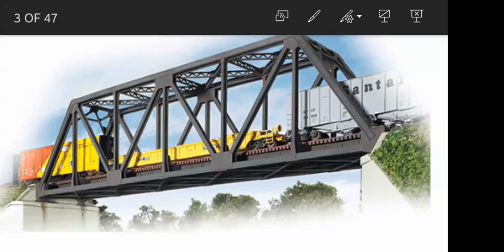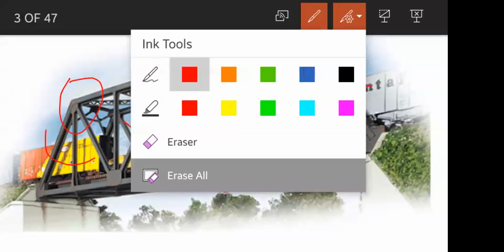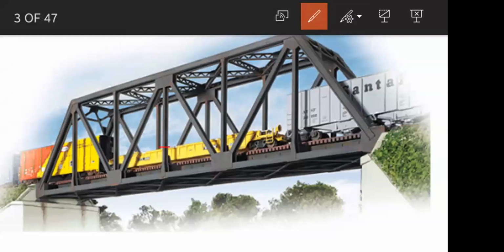Don't confuse. In the case of beams, we know static indeterminacy and kinematic indeterminacy. But in the case of trusses, we calculate external indeterminacy and internal indeterminacy. External means support reactions. Internal is related to how many joints are available in the given truss and how many members are available. Based on the equation m = 2j - r, we can decide whether the given truss is statically determinate or indeterminate.